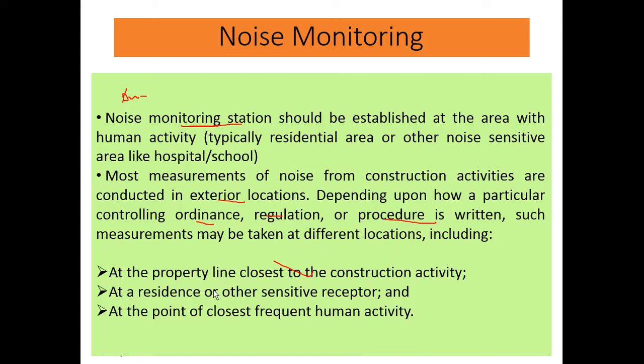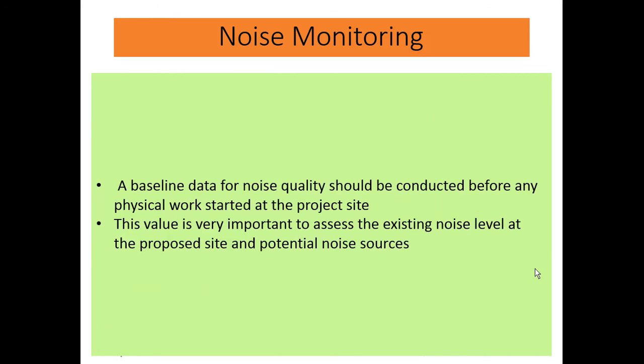Okay, I will explain. The location is a resident or sensitive point of closest frequent human activity. So you must look at this criteria for setting up the noise monitoring session. Similar to air pollution, the baseline data is important. Baseline data means the existing level of the noise before the construction activity starts. This value is important to assess the existing noise level at the proper site and potential noise sources.